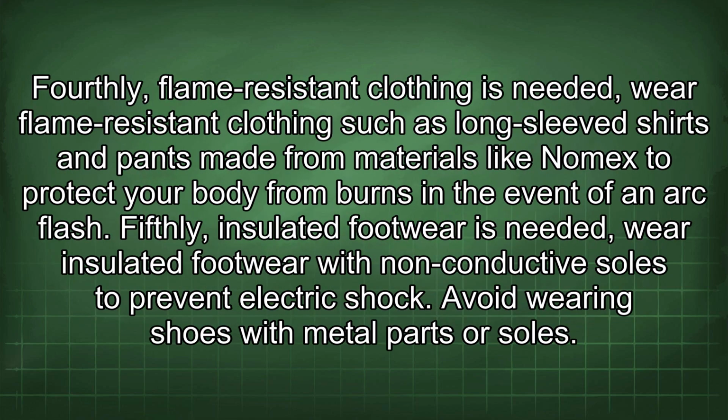Fourthly, flame-resistant clothing is needed. Wear flame-resistant clothing such as long-sleeve shirts and pants made from materials like Nomex to protect your body from burns in the event of an arc flash. Fifthly, insulated footwear is needed. Wear insulated footwear with non-conductive soles to prevent electric shock. Avoid wearing shoes with metal parts or soles.